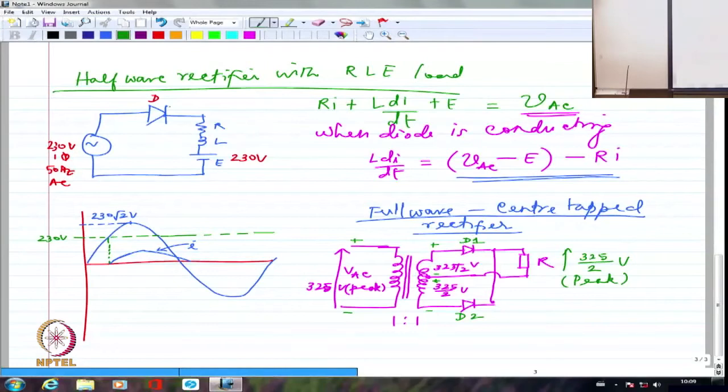Right. And one more thing is, when this diode is conducting, this is going to be a short circuit, right? Hardly any voltage drop. So essentially whatever is the voltage here, that voltage will come at the cathode of the other non-conducting diode. So I will get the same positive voltage connected at this point. And after all, this negative voltage is here.